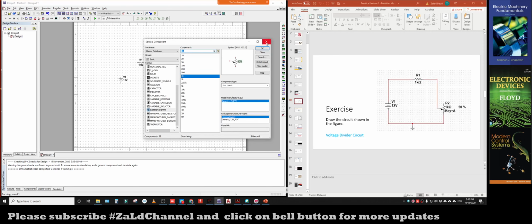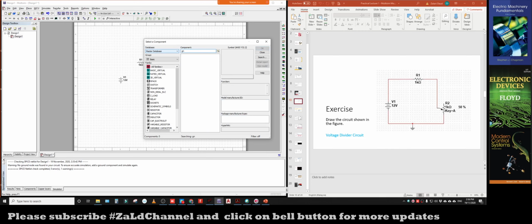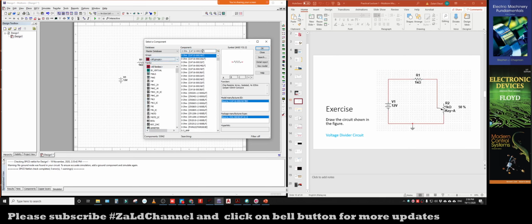Okay, so I have already placed the resistor. Then finally, I want to put the grounding, which is the returning point of the current, the common ground. Where's my common ground? Let's search for it. Otherwise, you can just search from here, GND. If you couldn't find it in component search, click on all family, and then find the grounding, GND. Oops, basic, all groups. Okay, all groups, then find the GND.